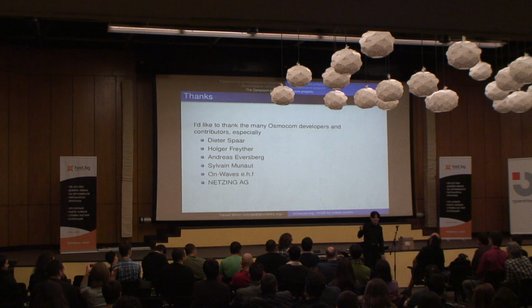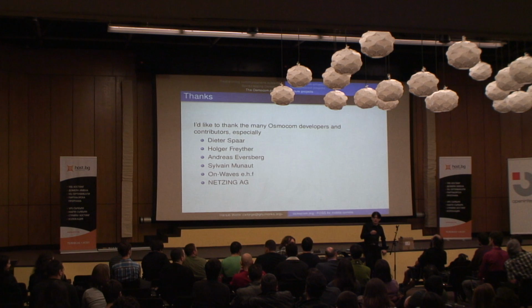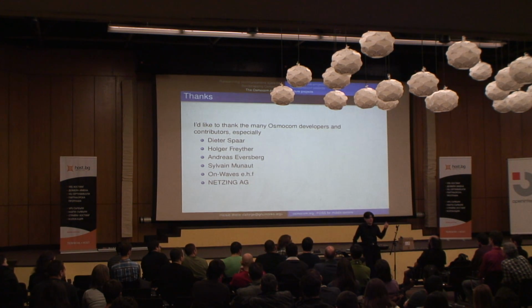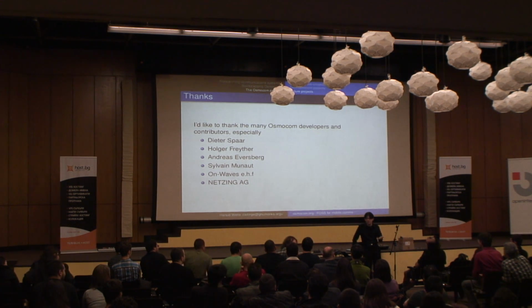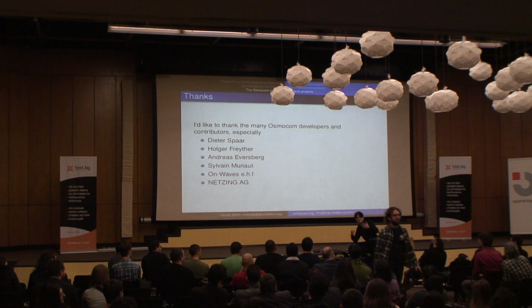So what he did basically is he started his own base station using OpenBTS and then sent malformed messages to the mobile phone, causing buffer overflows in the baseband processor. And from such a buffer overflow, he was activating the automatic answer mode of the mobile phone. So the next incoming phone call would be automatically answered by the phone without giving any indication. The screen is completely blank. It doesn't ring. It doesn't show you there is a call, nothing. It's because in the baseband processor, the next call was automatically answered. The application processor that runs all your user interface never got any indication that there was an incoming call. That was demonstrated with, I think, an iPhone 3GS at that time. This is a couple of years ago. And it was demonstrated with some HTC Android device, I'm not sure what it was. But fundamentally, those flaws are not specific to certain phone models.